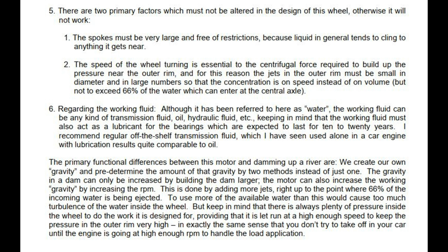This is done by adding more jets, right up to the point where 66% of the incoming water is being ejected. To use more of the available water than this would cause too much turbulence of the water inside the wheel. But keep in mind that there is always plenty of pressure inside the wheel to do the work it is designed for, providing that it is let run at a high enough speed to keep the pressure in the outer rim very high, in exactly the same sense that you don't try to take off in your car until the engine is going at high enough RPM to handle the load application.